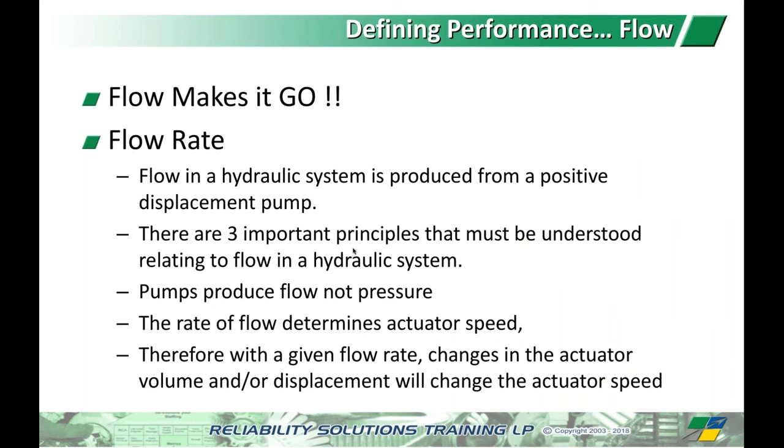And then, of course, the quality specifications for your parts. If I'm going to define the performance of a hydraulic system, there's certain principles I need to know. And probably one of the most important principles in the world of fluid power is flow makes it go. And basically, flow in your hydraulic system is what's actually causing actuators to move. Nothing moves unless you have flow. And the speed at which things move and occur is a direct function of the flow rate. And of course, the thing that provides that flow for us is the pump, okay?